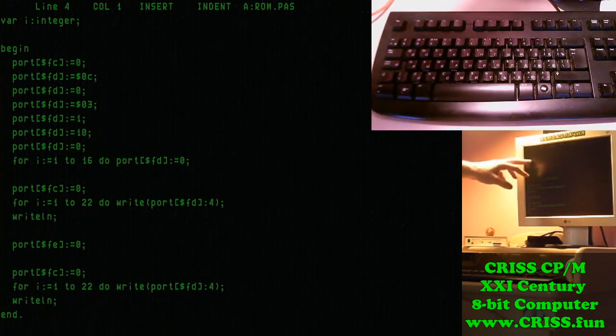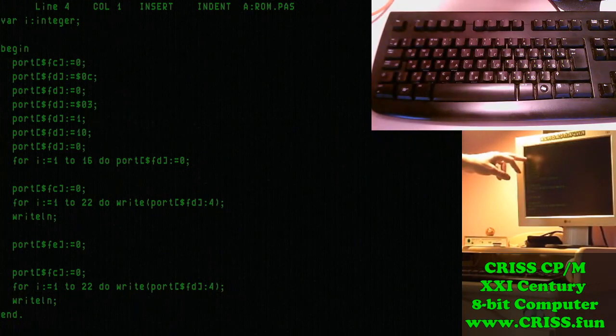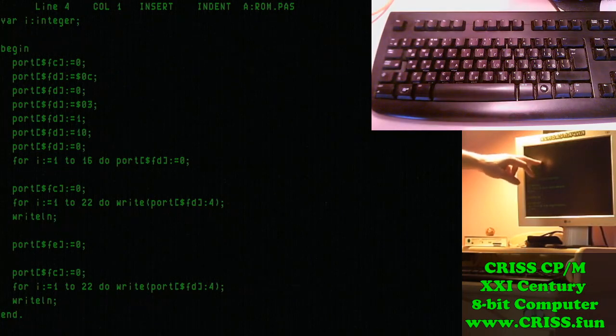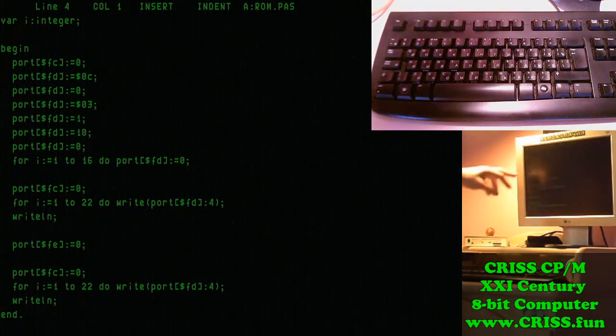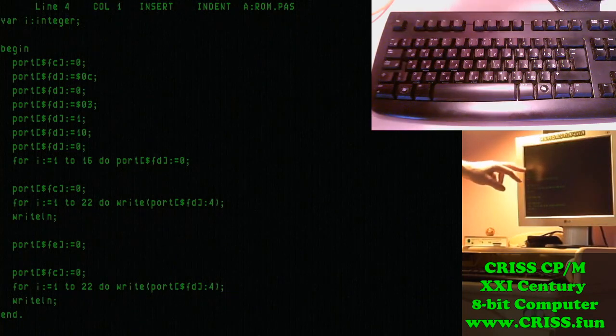Accordingly, the FC block is responsible for working with external SPI devices, and we sequentially write the device code there. 0C is the ROM code, then a special setting for the access speed. You can leave 0 by default. It will work at a frequency of 5 MHz. This is quite enough.